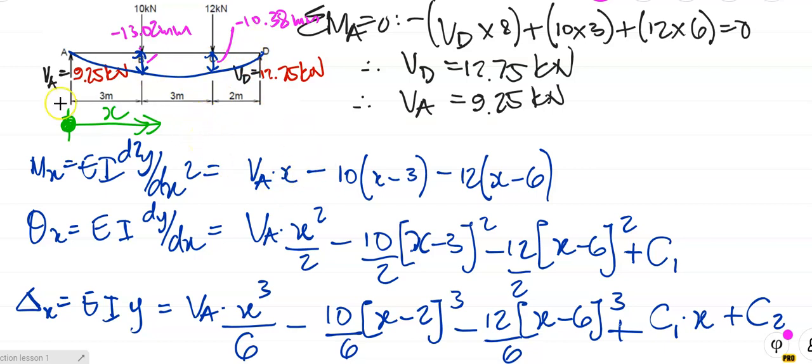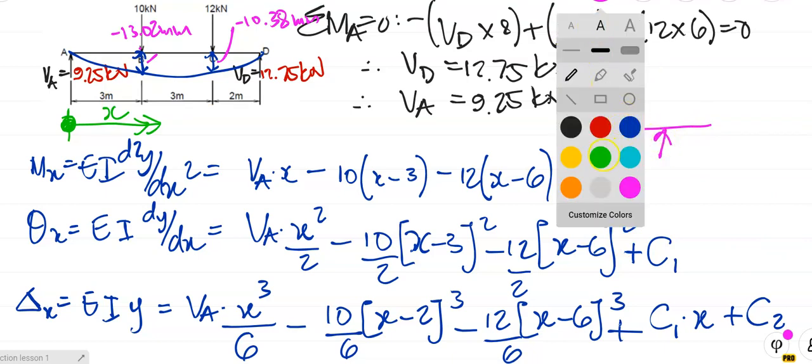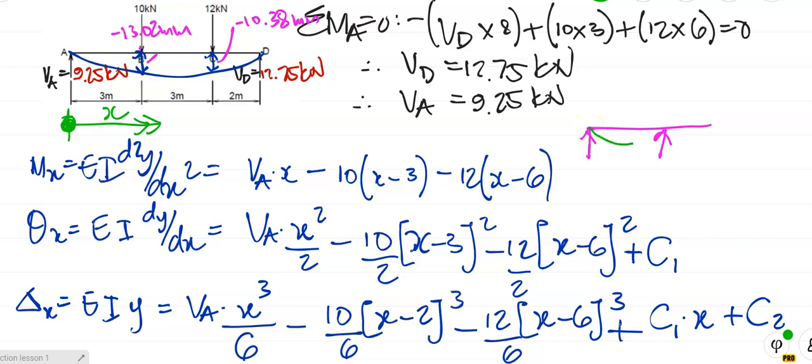Now sometimes we get cantilevers. If I can just sketch it here quickly. If you've got a cantilever over there, that beam will bend something like so, and it'll do that. So even though it's bending down there, that will be a negative deflection, small little d. And even though the beam is bending downwards over there due to the span and the loads here, the free end of the beam will actually lift off that point there, and that distance there will actually be a positive deflection.